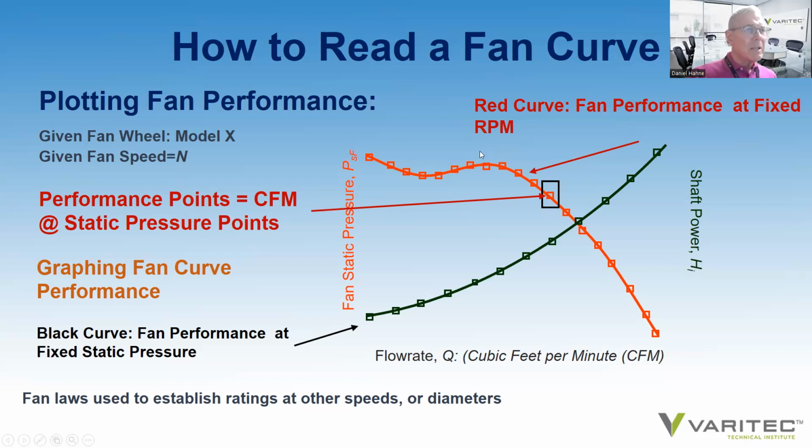You never select a fan with a performance point that is near to the top of or at the top of a stall point, because fan stalling results in reduced performance of the fan. It can result in excessive vibration, excessive noise in various conditions. So that's how the fan curve is generated, measuring airflow rates at varying static pressure increments in 1/10 increments.